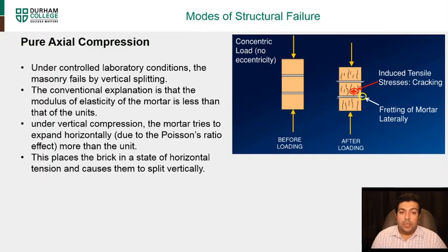If you're testing a masonry brick which has mortar, because of the vertical compression, the mortar tries to expand horizontally and comes out. That's the first thing that happens, and then the brick starts to crack and induces tensile cracking.